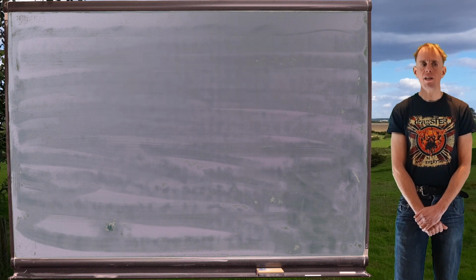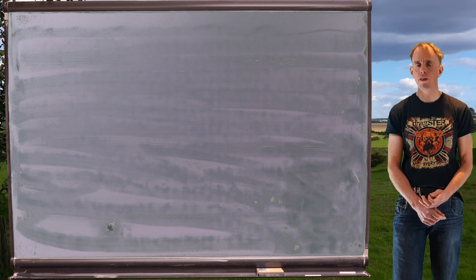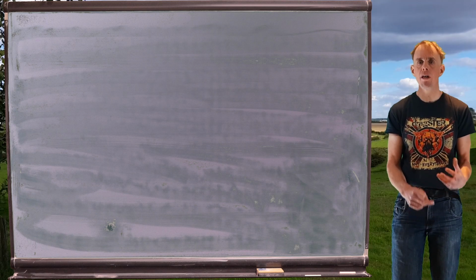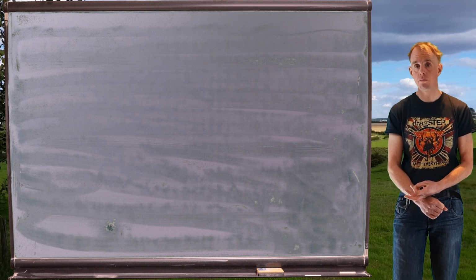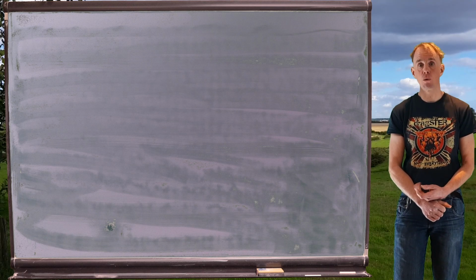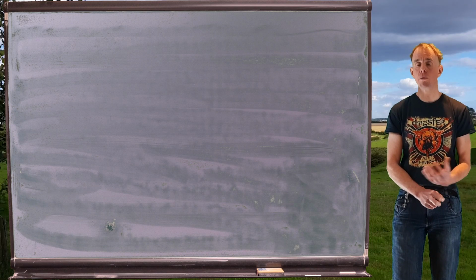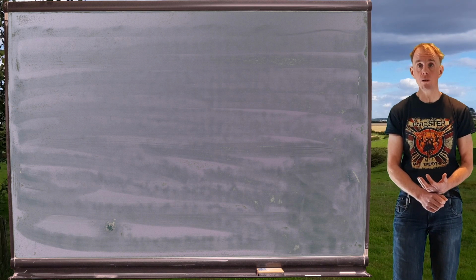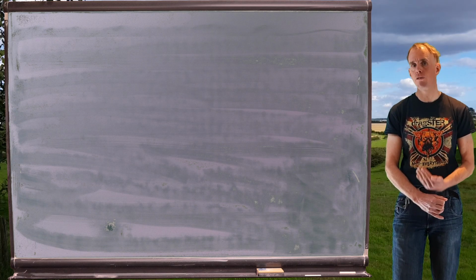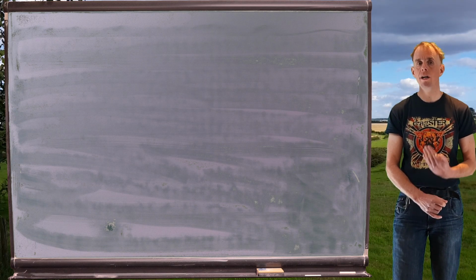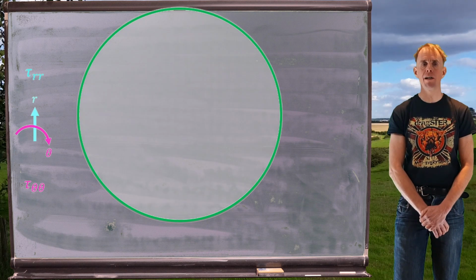So let's stick with the pipe to start with and think now in terms of forces. We're thinking in terms of normal stress differences to start with, but those normal stresses are going to result in forces. Forces will act to cause an acceleration, which means that if we've got a force imbalance anywhere, where we've got a net force that's non-zero, we're going to see some flow happening in a plane that is transverse, or 90 degrees, to the normal flow direction. So let's start by thinking about a pipe flow.